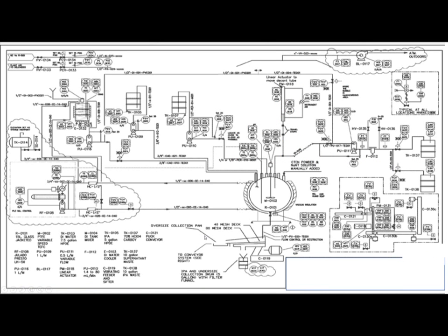So when a company decides they're going to build a plant or invest in a plant or extend a plant, they'll do it on paper first, and from that drawing they'll work out what equipment they need, what controls they need, what power supply they need, what mechanical stuff they need. And from that they can work out what maintenance routines are required, what maintenance frequencies have got to be done, and then they can calculate how many maintenance technicians they require to run this plant. And that basically forms the basis of your maintenance budget.